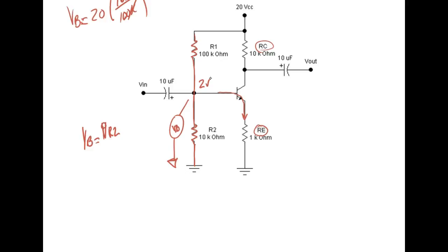Now, what you do in DC, you calculate RT, you divide it into the voltage to get IT, then you multiply it by this. There's no need to do that, because the voltage it drops is relative to the other resistors in the circuit. With the voltage divider formula, you do that without calculating I, right? You understand?